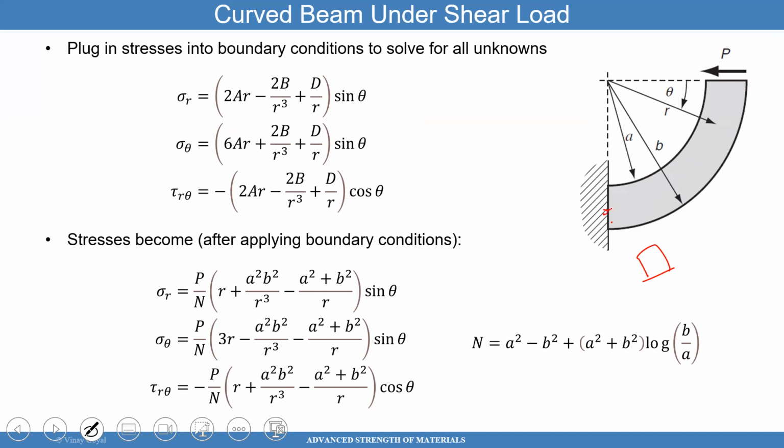So that point, say, has coordinates of, say, 5, 90 degrees. You should be able to plug that into this formula and get sigma rr, which goes this way, sigma theta theta goes that way, and the shear goes that way, sigma r theta. If I know the stress state in a square that I can draw, I should be able to use Mohr circle very straightforwardly. So that is going to come up potentially in the exam for you to practice.